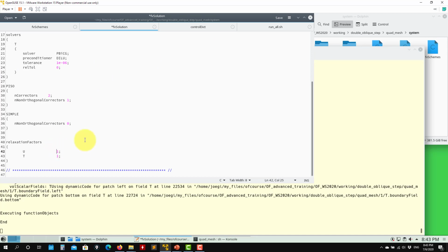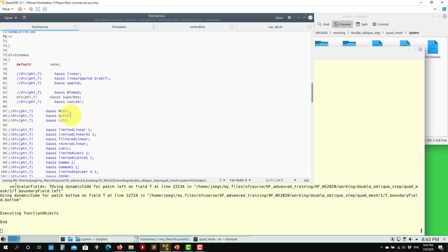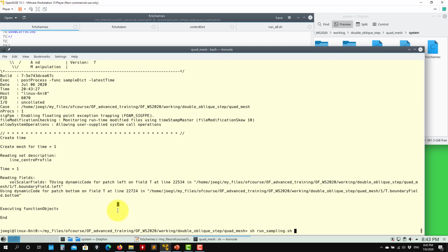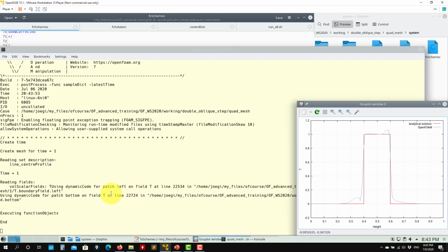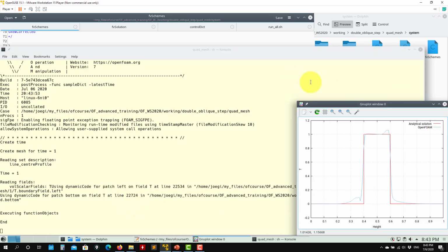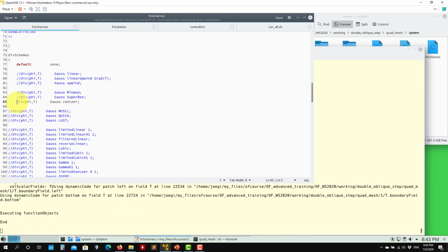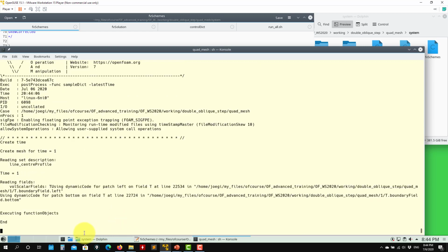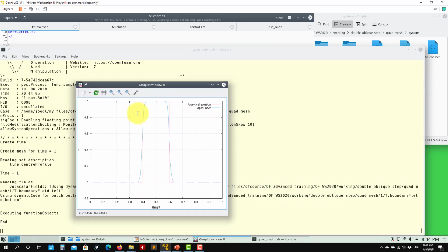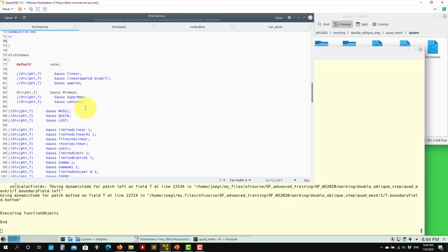So in this case, relaxation factors have a very important effect. So also you can get the feeling of the relaxation factor. We go now Van Leer. We do the sampling and see that oscillatory as well. And let me go, for instance, min-mod. We should have something similar. Okay, the min-mod is very stable. So I really like the min-mod.